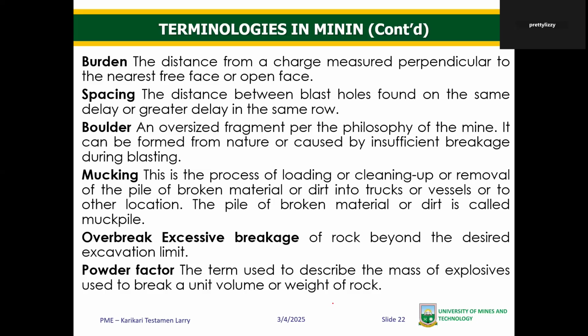So I visited a certain mine, I think Goldfields, and they were using something called blast sleeves. Before they pump the explosives into the hole, they put a rubber tube in the hole, and then they pump the explosives in. Then we do our stemming and finally we fire to get the size.